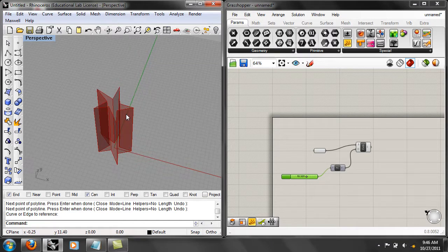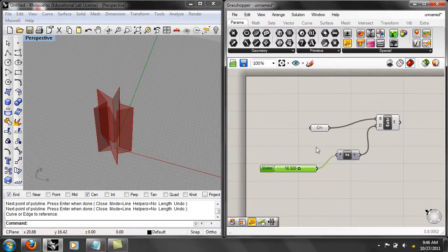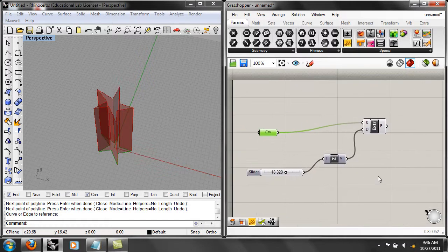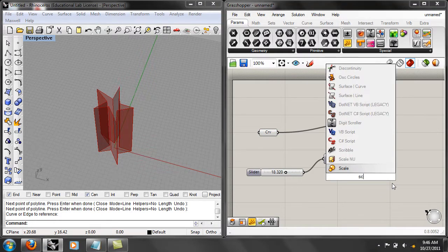Lofting? Not yet. But no, think about different things. We can move things, we can rotate things, or we can scale. Yeah, somebody said scale. Scale things. If we scale that section and then extrude it, we can actually get the kind of parameters we had in our parametric cylinder. So how would we figure out how scale gets in there? Type it in. Yeah, double click and scale. Oh my gosh, it comes right up.